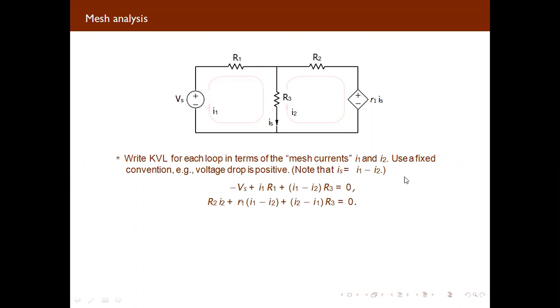Okay. You can see here. Now, when we are applying KVL to this loop, how can we apply it? What does KVL say? The algebraic summation of voltage for each loop will be 0. So, we can calculate the voltage for this, and the voltage for this. If we take the clockwise direction, R2 and the current flowing through this R2 will be I2.